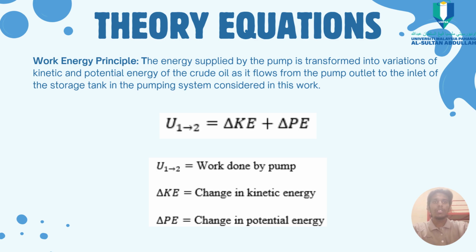And for the theory equation part, I'm going to explain the certain formulas that we use to conduct our calculation methodology. So first, I'm going to start with our work-energy principle, which asserts that the work done on a system is equal to the change in the total mechanical energy of the system. This energy supplied by the pump is transformed into the various kinetic and potential energy of the crude oil as it flows from the pump outlet to the inlet of the storage tank in the pumping system.